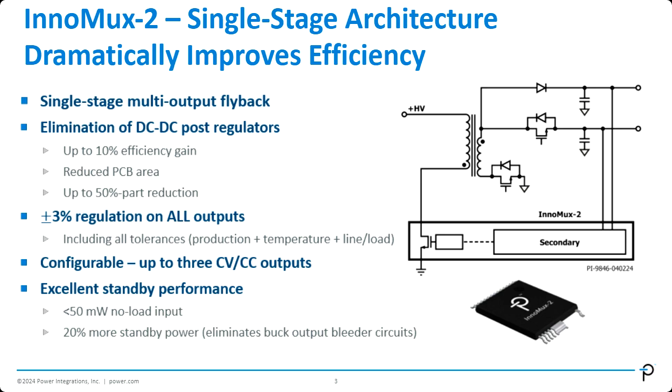But I'd say normally if you're running at, for example, full load condition, it'll run around 90 kilohertz, around 100 kilohertz with a 100 kilohertz device, or with a 130 kilohertz device, you can run up to 120 kilohertz, something like that.